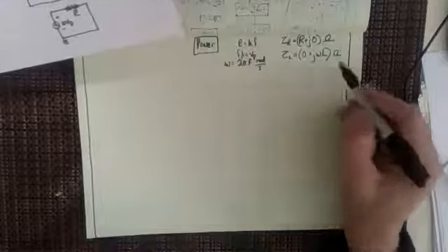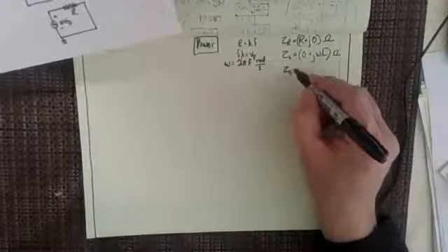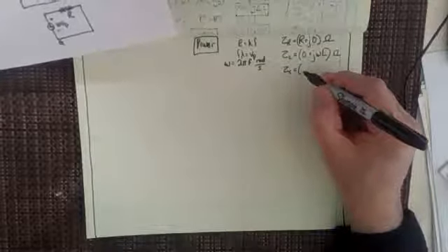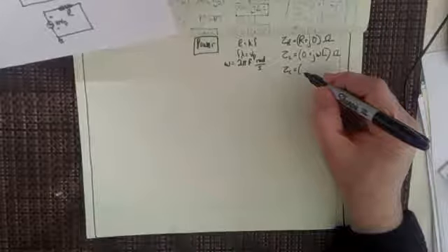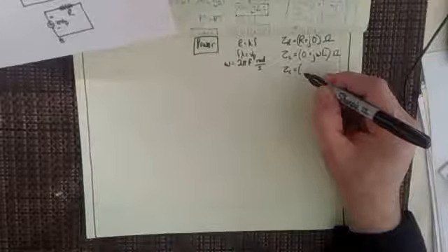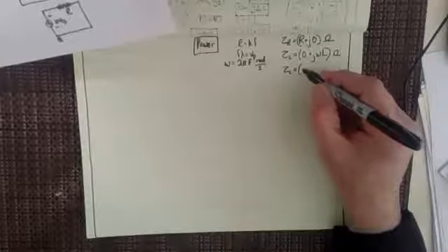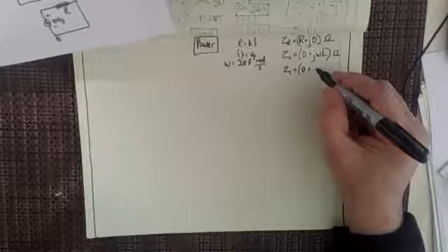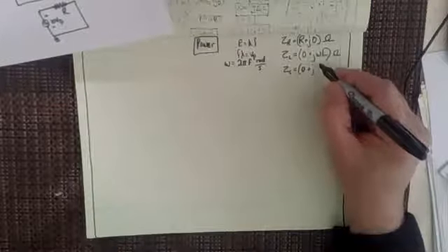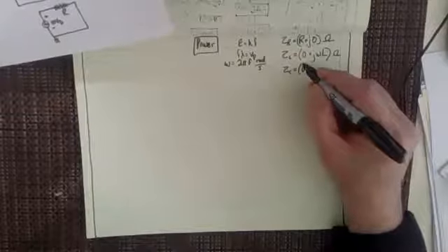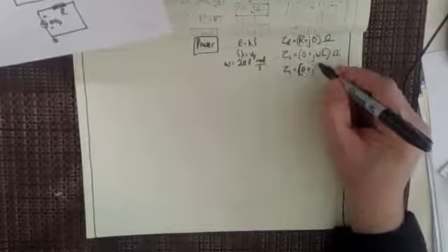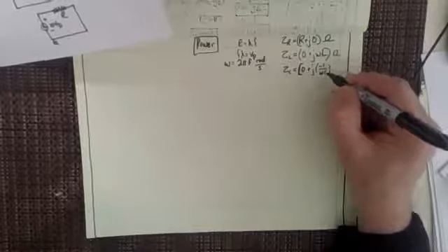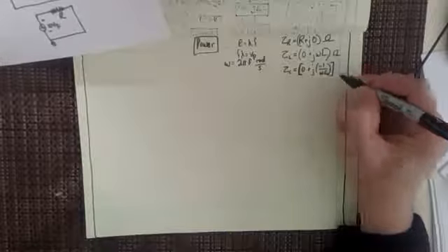As far as the three, I should say the capacitance, the first two, but the capacitance also theoretically, and this is much closer to realistic in real life capacitors than it is in real life inductors, it has zero resistance. Plus, now I like to say plus j, and like I said before, I like to put the -1 over omega C in the reactance instead of putting that negative out in front, right?